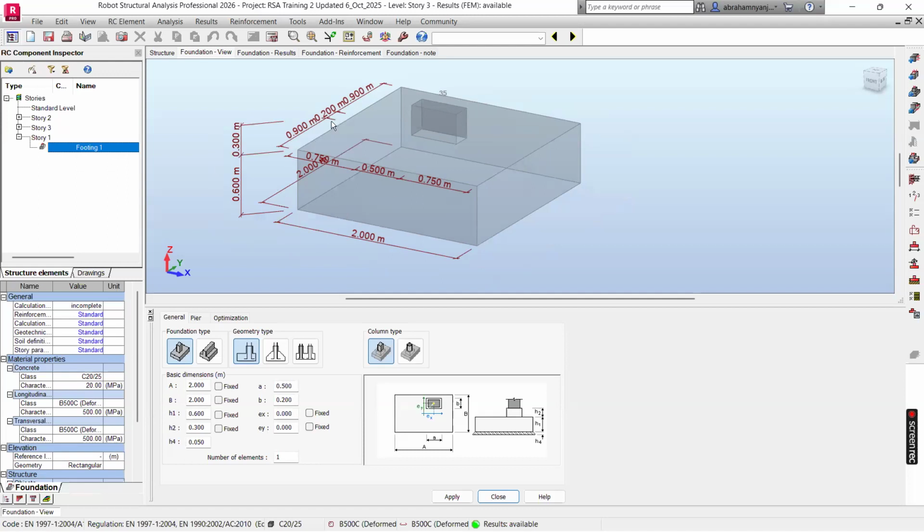So now, this is still the same procedure that we did earlier on. This is a footing, but we need to define properties, just like we did for beams, slabs, columns, so that the software can now design this foundation using those specific properties that we have defined that are specific for foundations. They are right here, so we are going to just go through them, customize them to what we want. Then later on, adjust them here and run the calculation.